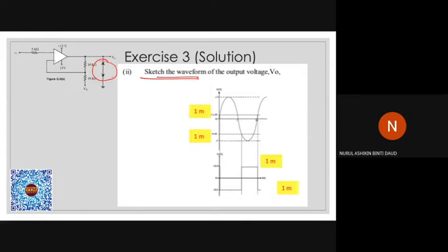The reverse against Zener diode, because one of the Zener diodes here is at the negative side. This is the reverse side. So this one, the value is minus 3 volts here. And the value here will be 5.2 minus 0.7 for this part.